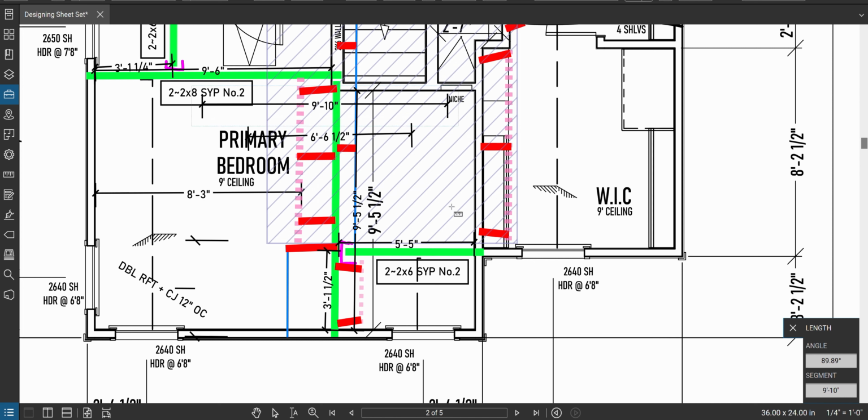All right, so that's that tributary width, and then I have a different tributary width for the front 3 feet of this beam because the room changed. So I'm holding the ridge, and I've got a purlin bracing on the beam too. All right, so I'm going to go from the ridge to the wall halfway, and then from the purlin to the wall halfway.